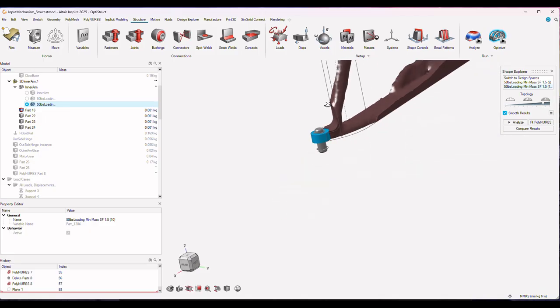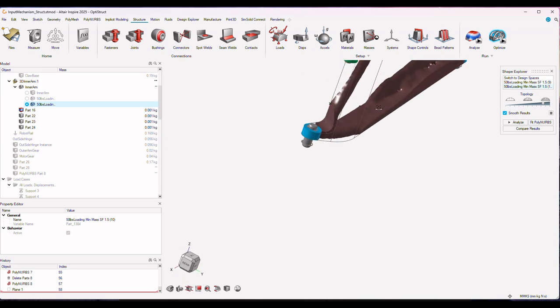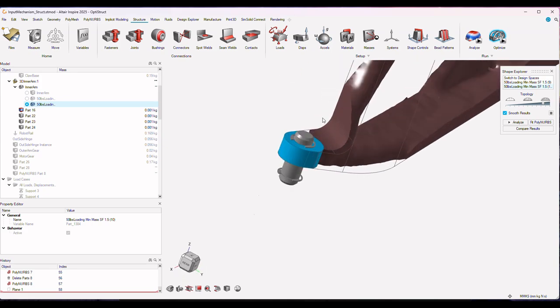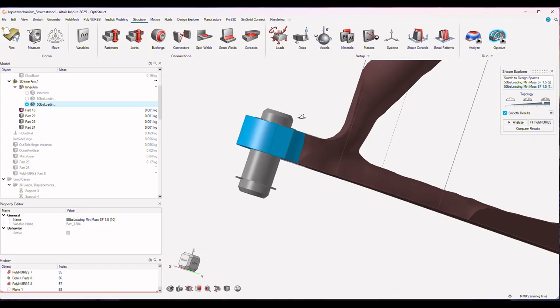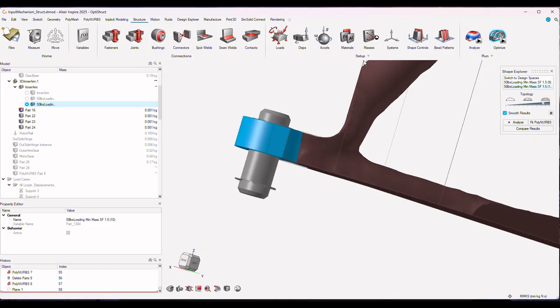You look at the results and you see that the results are right along the side here. So I would probably keep this, whatever I'm putting in here. If I'm putting in a bolt, I'm not locking this down because this needs to be a hinge, but putting a bearing or whatever, I would try and keep this line of action, right?